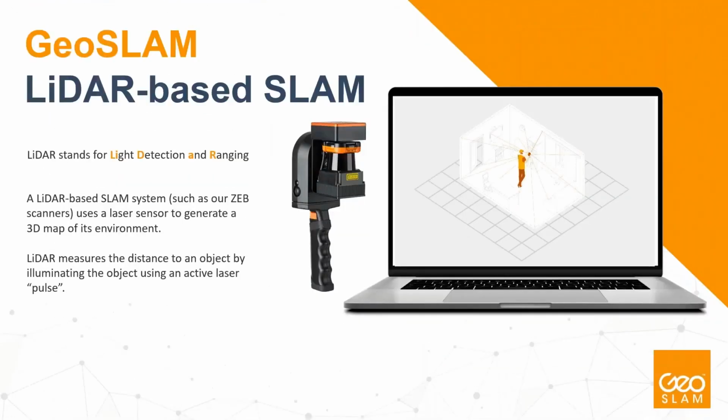We're a LiDAR based system. So LiDAR is light detection and ranging. LiDAR utilizes a laser sensor, and we spin that laser sensor around so we can collect all the data around us, so we can locate where we are in the environment around us. What we also have is an inertial measuring unit, an IMU, on board, which detects any changes in the movement of this sensor. So using those 2 data streams, we can map a whole area around us. It is that simple.